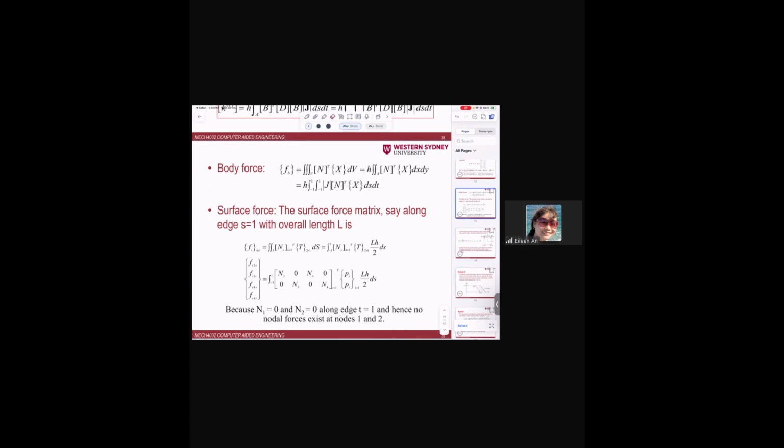But if we decide to use a numerical method, we have to make sure the entries in the force matrix are point loads. But in the real case, there are body forces and surface forces. So we have to convert those kinds of forces to their equivalent loads.